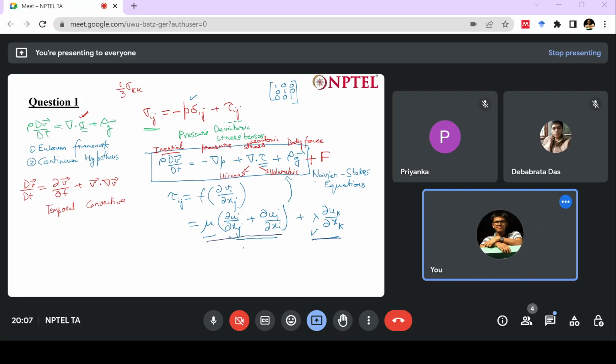The second is associated with linear strain and will dictate the volumetric stresses. So it has these two components, and also body forces. By breaking down the stress tensor, we are now in our fluid mechanics region. This is the generic Navier-Stokes equation.